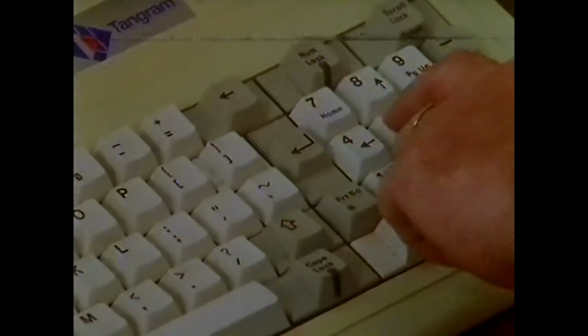If I want to draw, for instance, a line, first of all I pick a point anywhere there. And from that point, if I want to draw a horizontal line, I put the cursor roughly horizontal from the point. L lets me pick up a length, and then I put in the length I want, and we get the line. Same thing again for horizontal, L and then 50. And then to complete the rectangle, I don't need to put the distance in. I merely pick up the end of the line I've got by pressing the J key, which closes the rectangle.